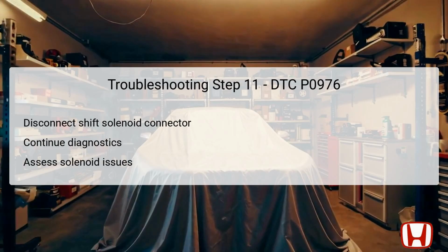The final step in this troubleshooting series requires you to disconnect the shift solenoid wire harness connector. This disconnection allows for further testing and eliminates any potential interference from other circuits during diagnostics. With the connector removed, you can conduct more targeted tests on the shift solenoid itself to determine if it is indeed the source of the problem.